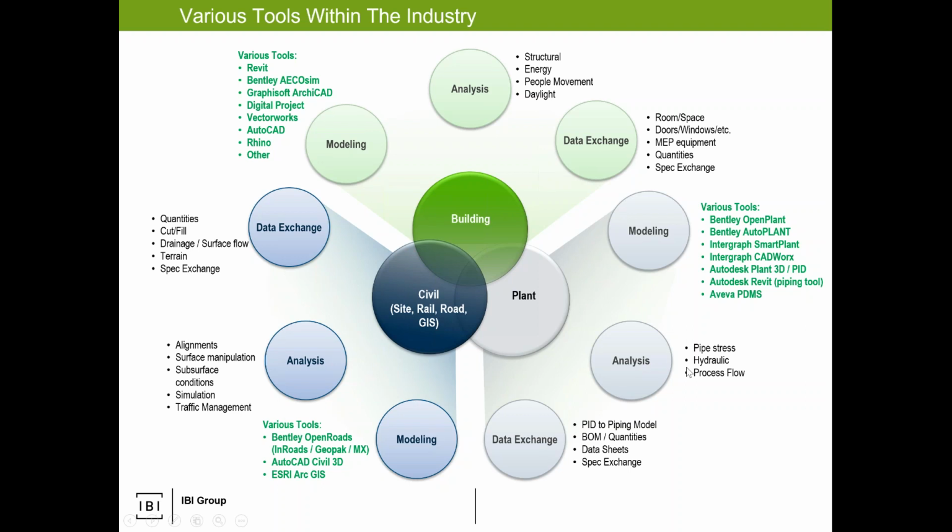Then on the plant end, these are very specific analytical pieces. So I would work on treatment plant models where it says, if I have a pipe that's 5 inches or a foot in diameter with this type of pressure, this type of material, of this temperature, flowing at this rate, will it burst? If I turn it 90 degrees, will the elbow burst? That's your pipe stress analysis. You can't do that if you're not using proper plant-based tools.